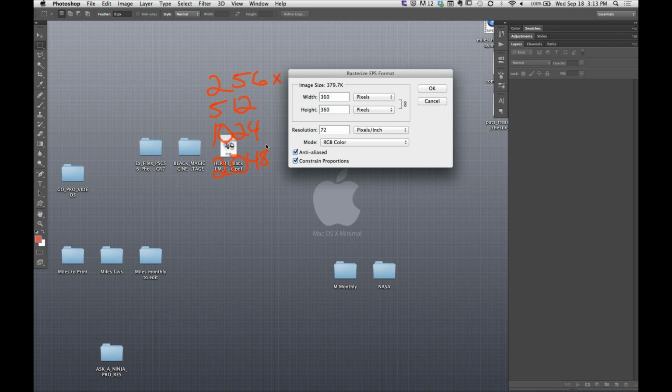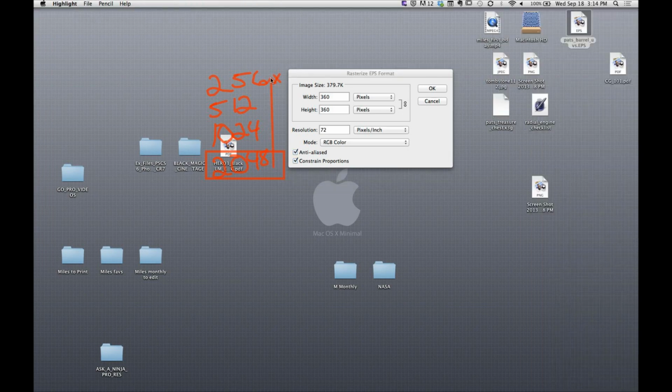So I'm a big fan, actually, of authoring at higher resolutions and then downsizing my image to meet whatever my needs are. I think that's a really flexible workflow. I know a lot of folks that author in 2048 by 2048, and then they use that downsizing system to move everything down in size and in quality as well. So I find for the most part, 1024 is kind of the minimum. But authoring at 2048 is not a bad idea. I author almost everything at 2048.